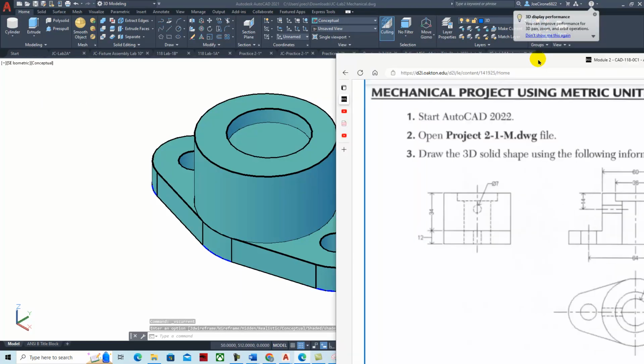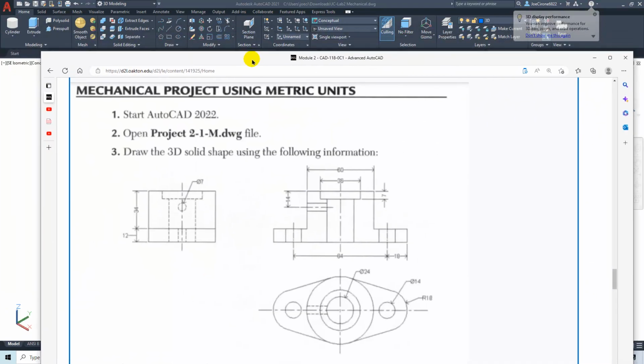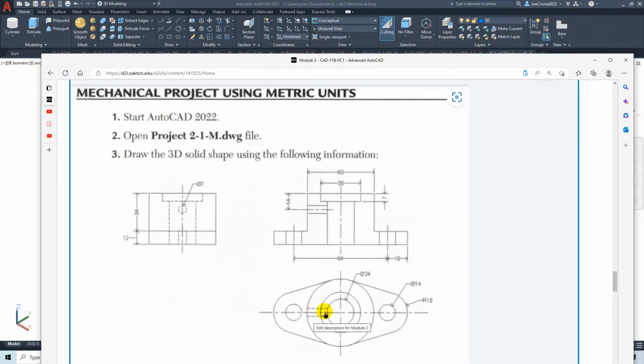Now I didn't union the bottom on it yet. I will get to that. But there's only one more feature that we need, and that's this hole that comes in at 14 millimeters off and to the side. Those can be a little bit tricky to put in because we're looking at a different orientation. This is a good reason for us to have that point at the 0 position, or at the center of it.